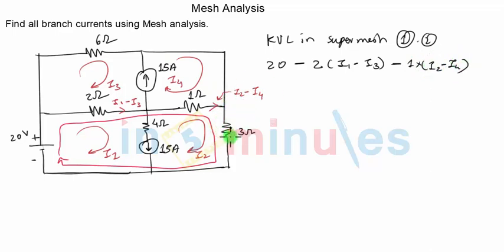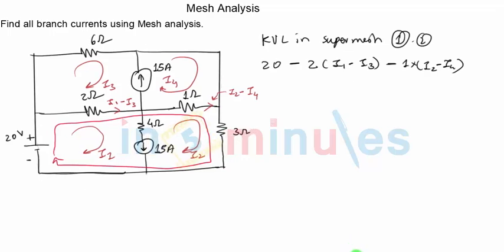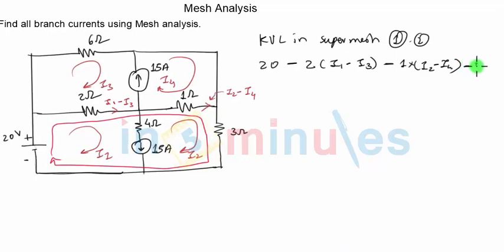Next, there is one more resistance which is 3 ohm, but it is simpler compared to the previous two because the only current through 3 ohm resistance is I2. I'll be traveling in downward direction, so does I2, and hence this will be negative drop again, so minus 3 I2 equal to 0. So let's simplify this.